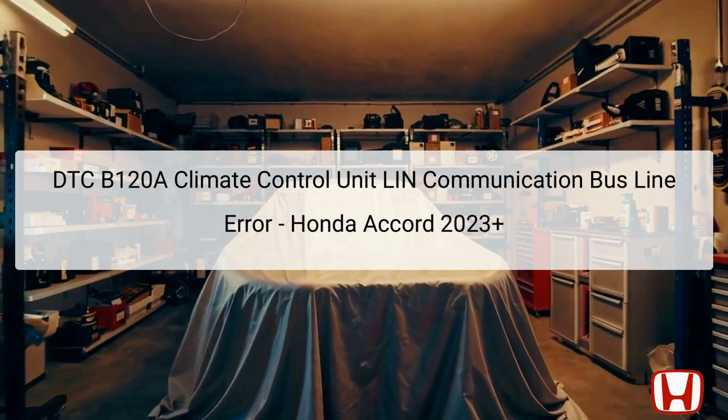This DTC is triggered when the climate control unit detects a bus-off condition in the LIN, meaning communication has failed continuously for a predetermined number of attempts. When this occurs, the climate control unit considers it an abnormality and logs the DTC for potential diagnostic purposes.